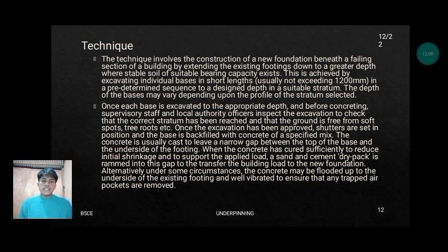Once each base is excavated to the appropriate depth and before concreting, supervisory staff and local authority officers inspect the excavation to check that the correct stratum has been reached and that the ground is free from soft spots, tree roots, etc. When the concrete has cured sufficiently to reduce initial shrinkage and to support the applied load, sand and cement dry pack is rammed into the gap to transfer the building load to the new foundation.